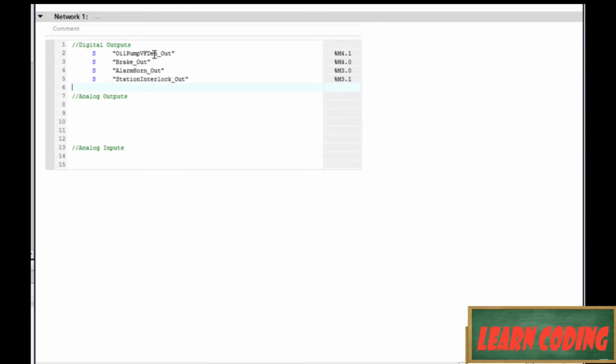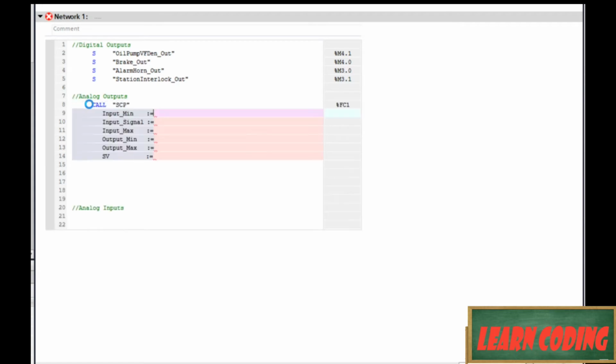They're set. Like I said before, we're going to have to come back to those once we do our HOAs, but for now, that got real easy. Now, we need to do our scaling, so we're going to drag that function in here. And hey, this ought to look really familiar, right? So for our min, our input min is 0, 27,648 for our input max. And since these are our outputs, we were going from 0 to 100 to start.